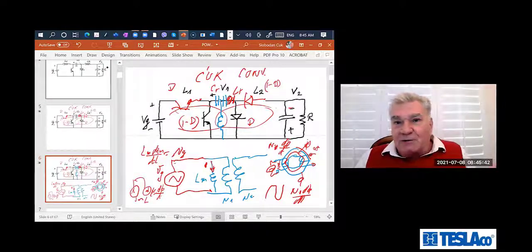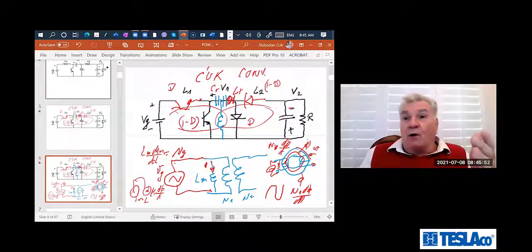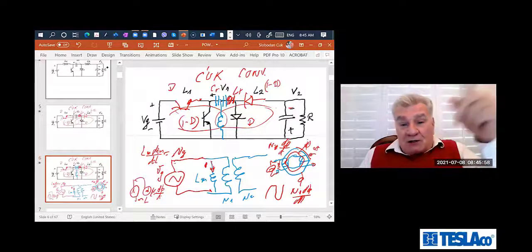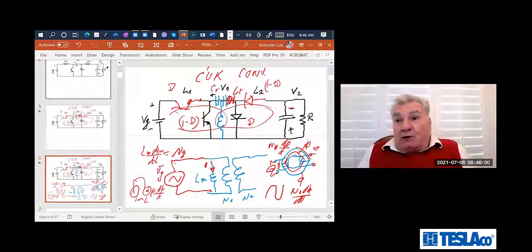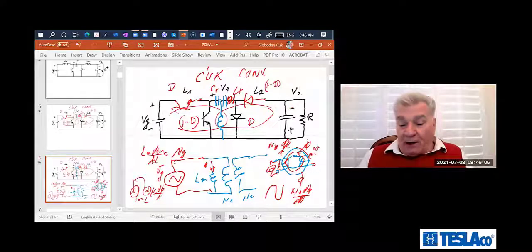So 60 Hertz was great because you have a huge inductance and therefore a small magnetizing current. Later, that wasn't good enough. Iron cores were not good enough. So some magnetic manufacturer invented Metglas, and Metglas has a 10 times smaller magnetizing current. So this wasteful current during the night is reduced 10 times. That's great because now you're reducing weight when it's operating open loop.